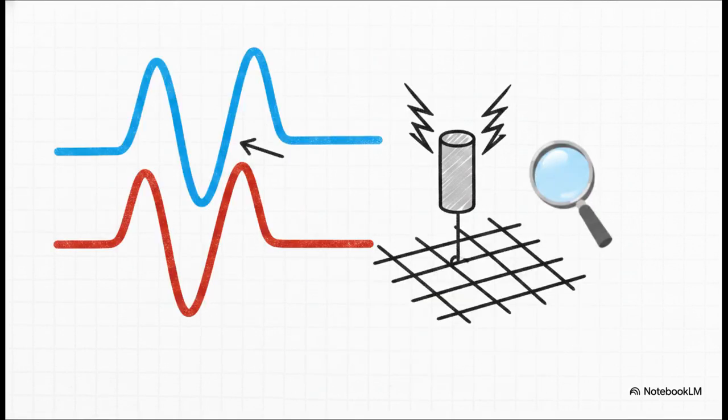Let's define this clearly based on the IEEE standard. DC offset is simply the difference between the symmetrical alternating current wave and the actual current wave during a transient condition. This unidirectional component can be either positive or negative polarity, and it won't change polarity. Instead, it just decays at a predetermined rate over time. What this means in practice is that the initial hit to your substation, especially your grounding grid, is far, far worse than a simple symmetrical AC wave suggests.